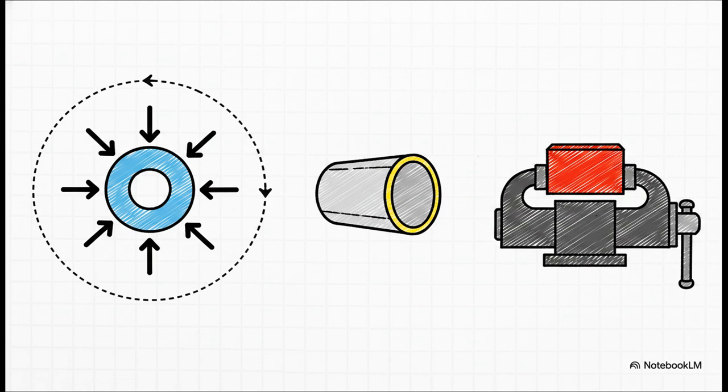But you've got to keep your material condition modifiers straight. We know MMC grants bonus tolerance for clearance fits. There's also LMC, or least material condition, which is absolutely critical when you need to preserve minimum wall thickness. But here's the catch. If MMC or LMC aren't specifically called out, the ASME standard automatically defaults to RFS, regardless of feature size. RFS grants absolutely zero bonus tolerance. It's super strict, but sometimes that's exactly what highly critical, rigid designs demand.